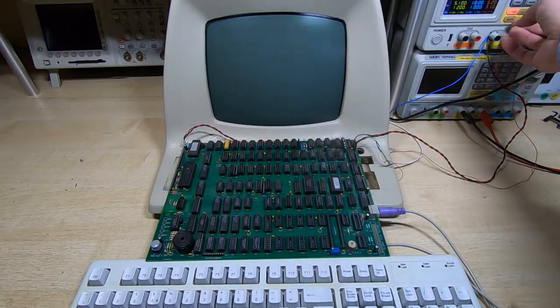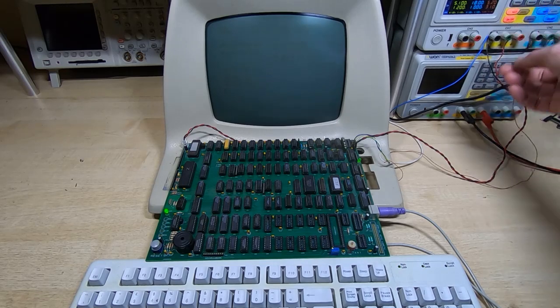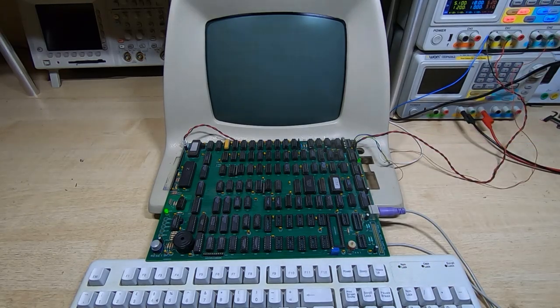It'll take a few seconds for the CRT to warm up. Got the LED attached still so we can see if the self-test completes, which it has done. And we've got the startup screen, which is very promising indeed. Still saying version 4 of course, because this is the ROM out of the version 4 board. But I can't see any artifacts. It's nice and clear. It's much clearer than it was on the previous board.